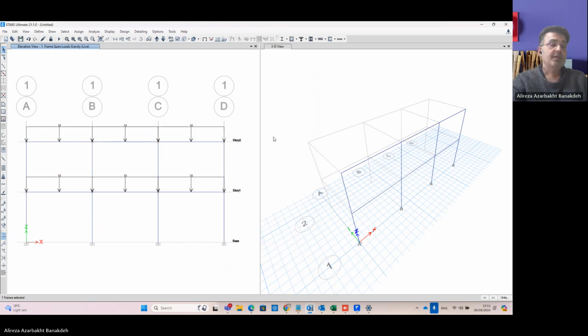So if you want to be more precise, you need to go to your detailing for the slabs in terms of dead load and live load. Go to the Eurocode to see what kind of live load you will get for your case example. Today, the focus is on how to model the soil structure interaction, and that's why we are going with arbitrary values for the section properties or the load cases here.